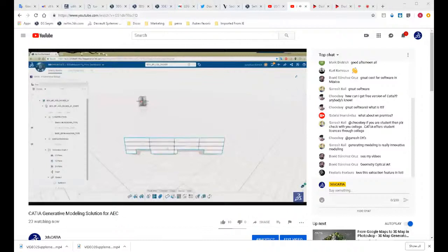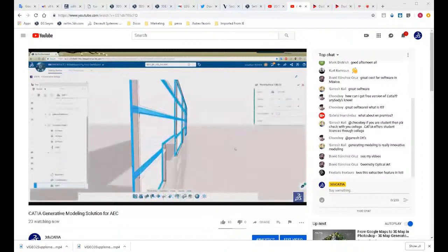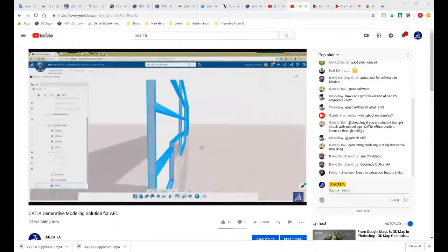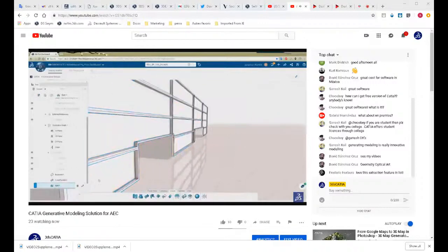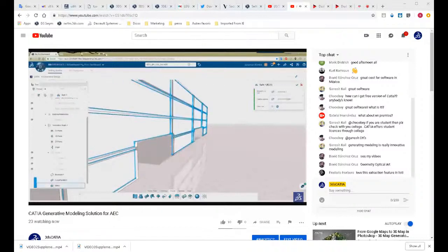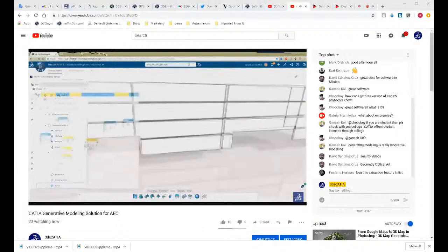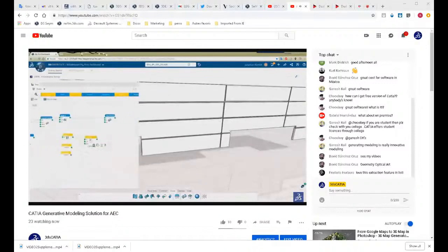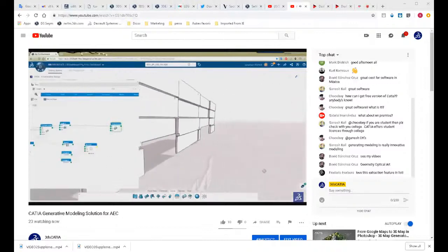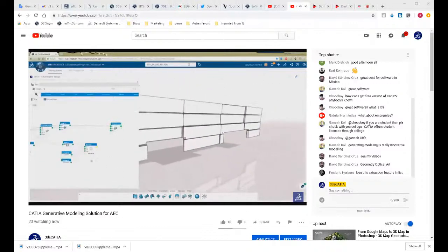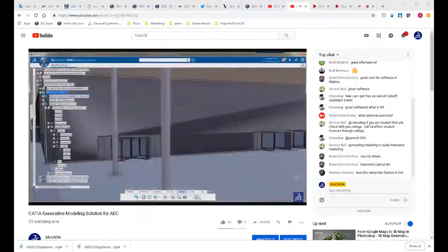We'll start by making a quick divide. We'll take the boundary curves of those divided elements. We'll offset those curves, and then we'll extrude those curves. We're doing all of this in the 3D immersive environment. At any point then, once we're ready to modify the logic of our model, we can open up the graph. Here I've added a random value operator to produce variation within my model. And then once we've created this model, we can save it, go back to CATIA, do a selective refresh.